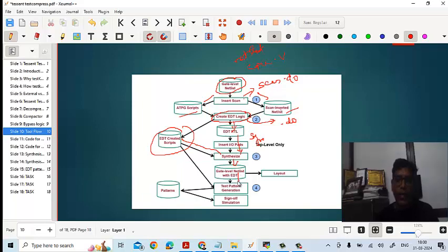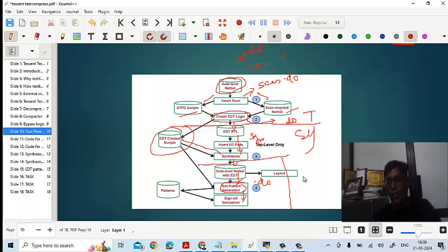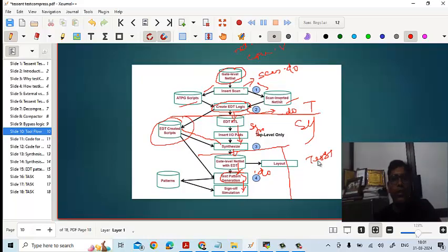Now this will be passed to the Tessent tool, and again the test pattern generation .do file will be run to generate the test patterns, and finally see what the fault coverage is. All these things happen using the pattern which has been generated. So the whole flow is: up to here this is Tessent, here it is Synopsys, and again this is Tessent. So we will do this one by one.